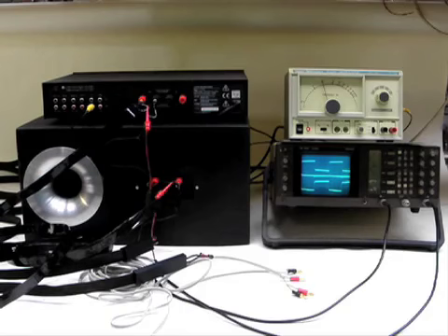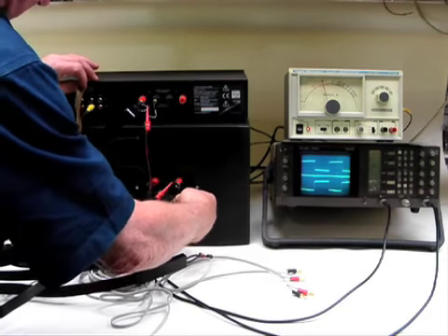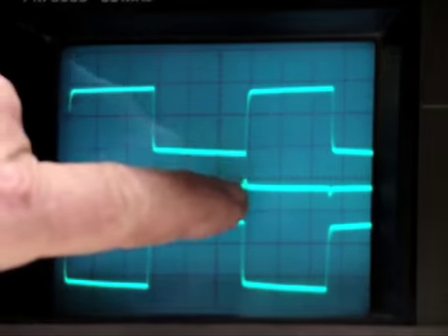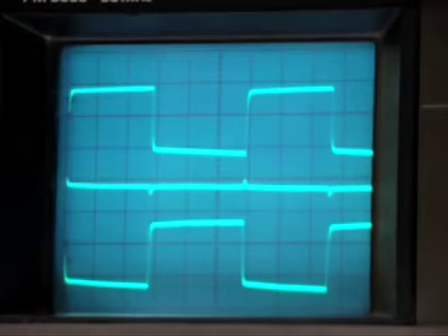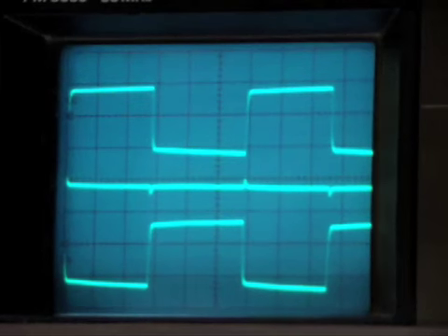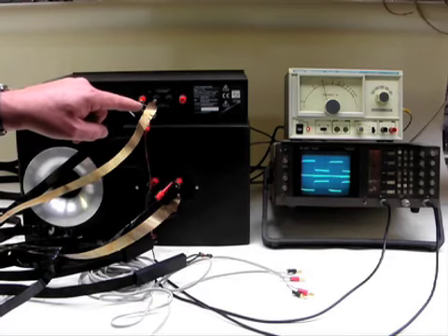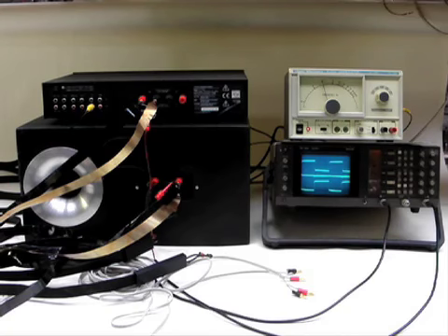That signal is being transmitted through the oscilloscope probe, so I'll put this one on here to short out that one, and you can see now we have the same little glitches there, which shows that it's the geometry of the cable, not the DC resistance of the cable, which causes these little anomalies. And those little spikes there cause distortion to the signal.